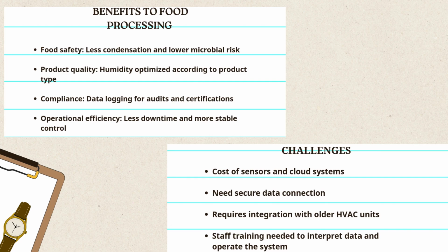Firstly, installing sensors and cloud systems can be costly. Second, a secure data connection is needed for continuous monitoring. Third, older HVAC units may be difficult to integrate with new technologies, and staff must be trained to understand the data and operate the system correctly.